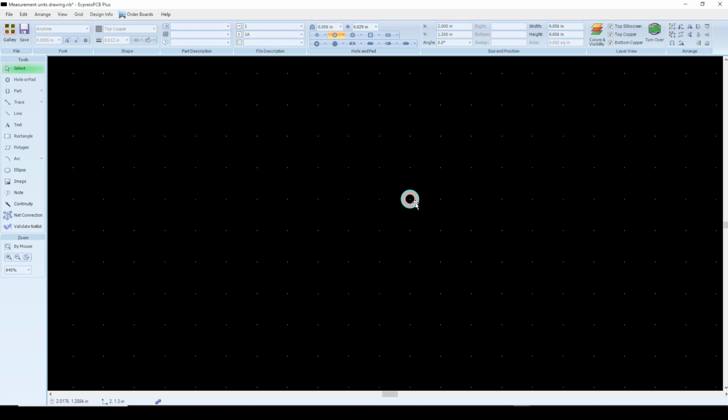Now, if you're working with really small snap values, say 0.0125 inches, meaning that there are 8 snap points between this point and this point, and 8 between this point and this point, etc., etc., you might want to zoom in while you're moving the entity. And let me show you that real fast.